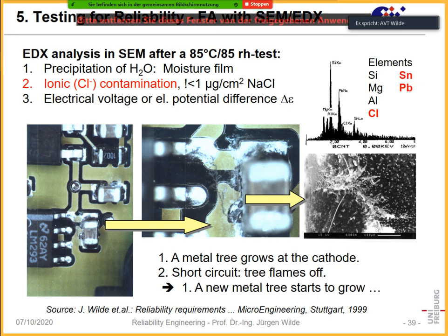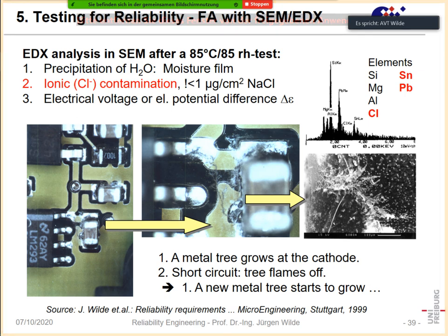On the other hand, you must do a coating after the soldering, and of course that coating is costly. So you do either some lacquering or you put on some silicone potting, but in the end it costs money, and so people want to save it.